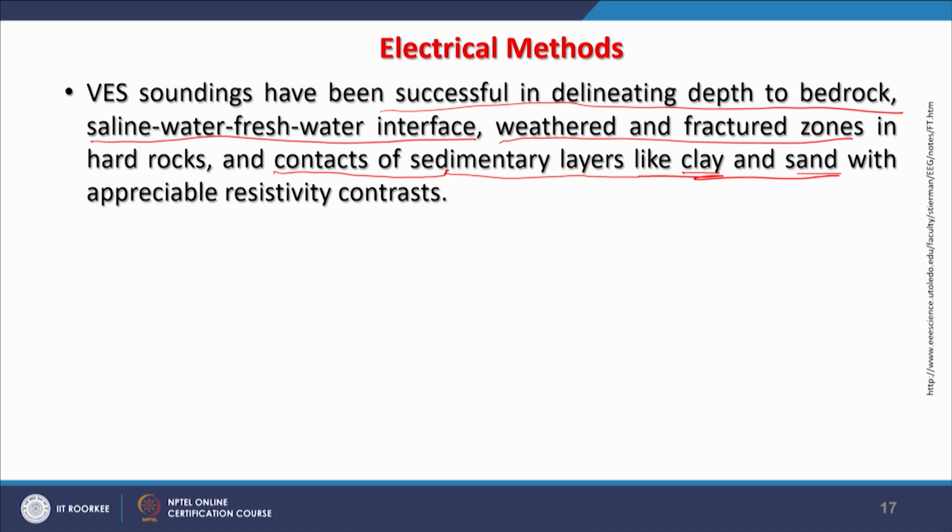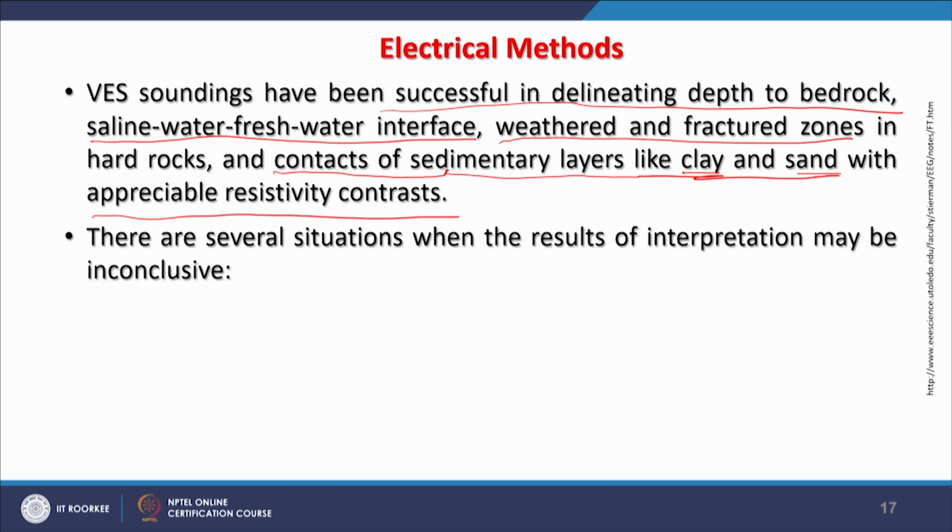The reason is, as we know, clay sediments are very fine grained, whereas sand sediments are relatively coarser. So, the contrast through this electrical method, especially VES, can be detected very easily if the layers are arranged like this. An appreciable resistivity contrast would be there, because clay is not good from a groundwater perspective, whereas sand is very good from a groundwater perspective. So, we are looking for such contrast,